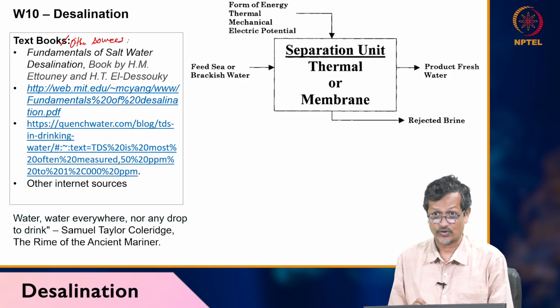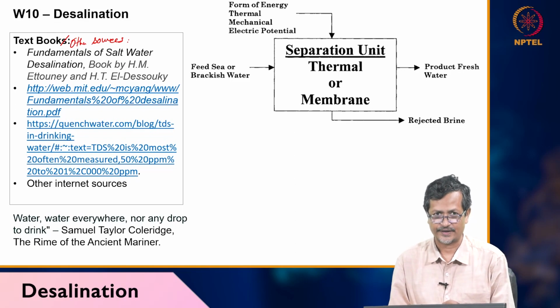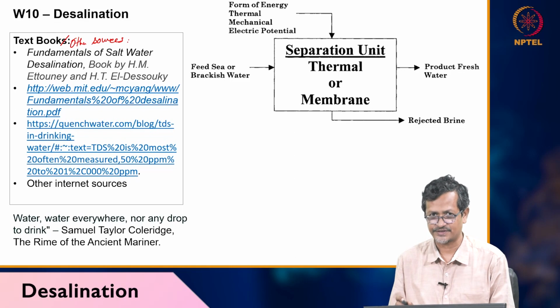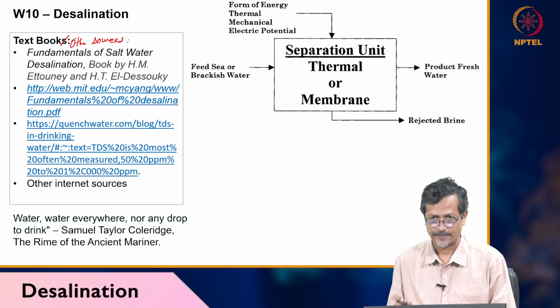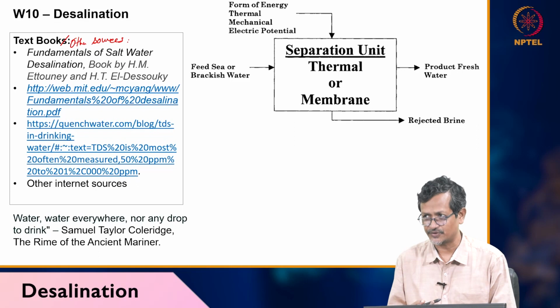So you have to reduce the amount of salt content in your water. Not only salt, if any bacteria or other contaminant is there, you have to remove that, then you can drink it or use it for other purposes. For ship and offshore platform applications, there will be boiler systems. A boiler system needs desalinated water, with no iron, no salt and no minerals in the water. If you have mineral or salt content, it will get deposited in your boiler pipes, and finally it will fail.